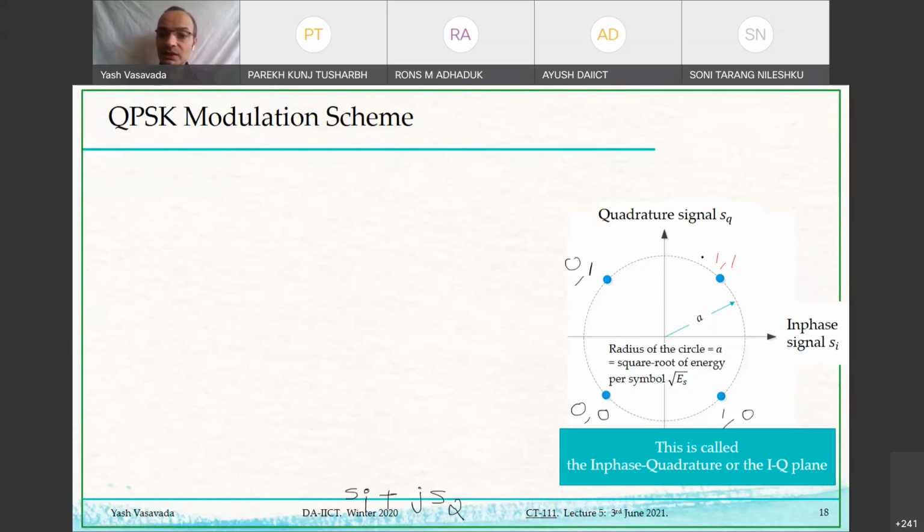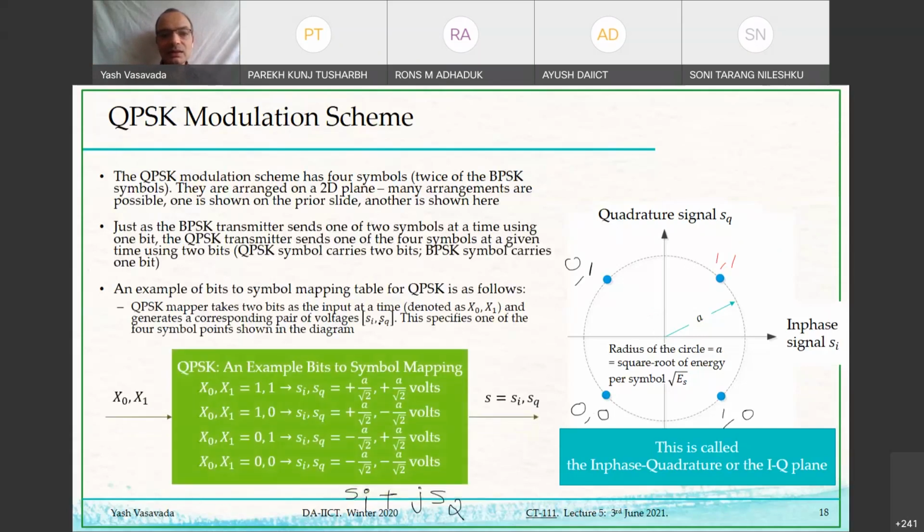And that is the actual physical radio frequency electromagnetic wave that I will transmit when I am transmitting bits 1, 1 over one symbol duration, 0 to T_sym. Then over the second symbol duration, T_sym to 2 T_sym, maybe I'll get 0, 0. Then I will again take those same two G1 and G2 that we have specified just now, but now I will multiply them by different coefficients, minus square root of 1 over 2 and plus square root of 1 over 2, something like that. How I am multiplying G1 and G2 is given by the mapping diagram, and the result will be the weighted summation of G1 and G2 as indicated by this constellation point.